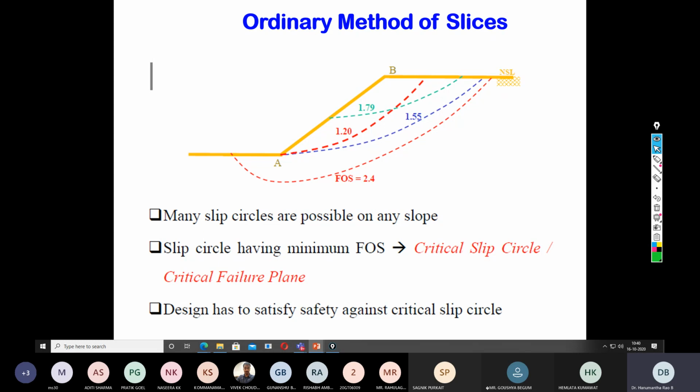This is one of the fundamental reasons we must stick to some kind of program for determining the factor of safety, whether it is the ordinary method of slices, Bishop's method, or phi equals 0 analysis. It is immaterial. But at the same time, you must understand that one has to take numerous trial slip circles in order to arrive at the least trial slip circle which is...